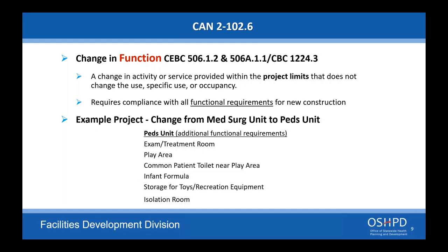Again, if you're just doing an equipment replacement on this generator, we're not going to make you relocate it because now it is no longer an equipment replacement. But there are things that you need to be aware of. And yes, you do have to meet current requirements for anchorage and so forth. But again, if there are existing conditions affecting that generator, such as the location, if it was installed in compliance with the previous version of a code, it does not need to be altered to be brought up into the current code.